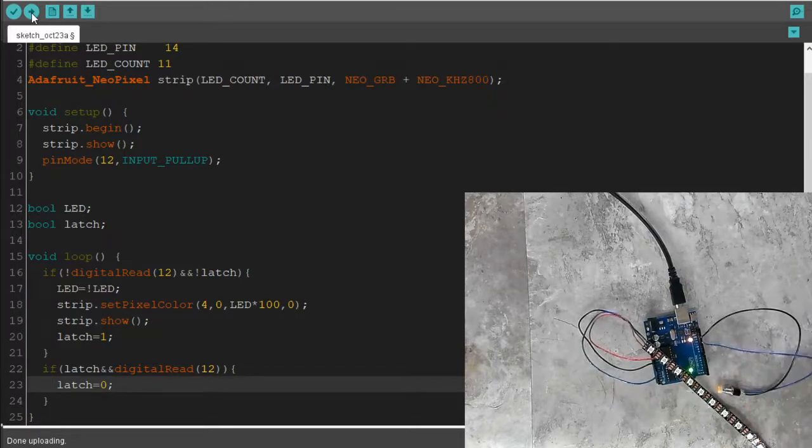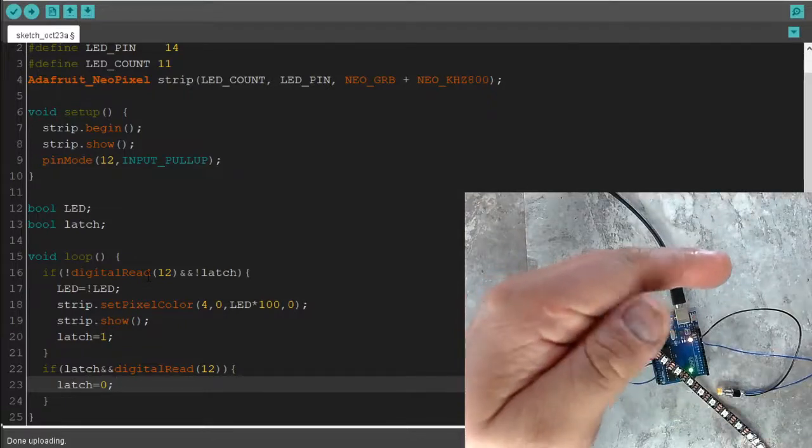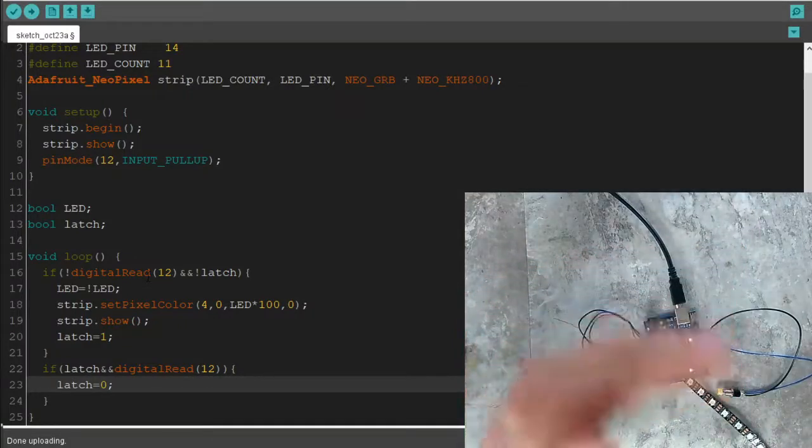Okay, that's because once I push it, the voltage comes up a little bit, right? So the voltage, well, I push it, the voltage comes low, kind of. There's a slight bit of electrical bounce in there that makes the voltage come high, right? And then I push the button, it's low. It doesn't quite go straight to low.